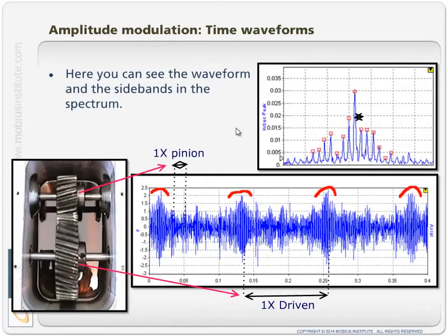In this case, and sorry these arrows have gone a bit funny, little technical difficulties that chew up time. But anyway, in this case we've got damage on this gearbox, some eccentricity on both of them, a little bent shaft in one case, eccentricity in the other case, just to simulate this fault. And so there's our modulation.